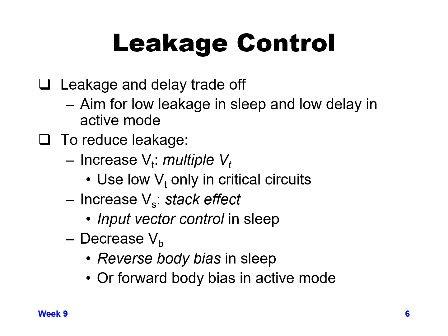And then finally, you can use reverse body bias, so you can change your body voltage or bulk voltage, depending on what you want to call it. Keep in mind, if you reverse bias your body, your VGS and VGB, or your bulk to source voltage, can modify your threshold voltage.